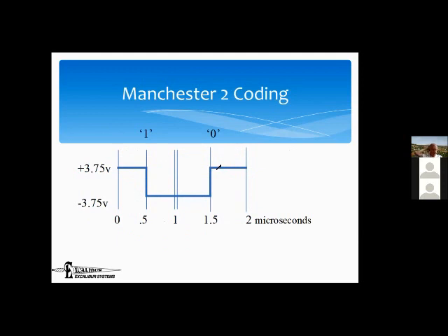Okay, so now what does this look like? Let's look at a picture of 2 bits. The first bit is a 1, and in this case, I say it's going down. That's partially true, and we'll see when I talk about differential signals why I'm hedging. But you see here, the bit time itself goes from this 0 to this 1, right? That's a single bit time, that's 1 microsecond. The middle of that, in a half microsecond, in this particular instance, you see that the signal is heading down.